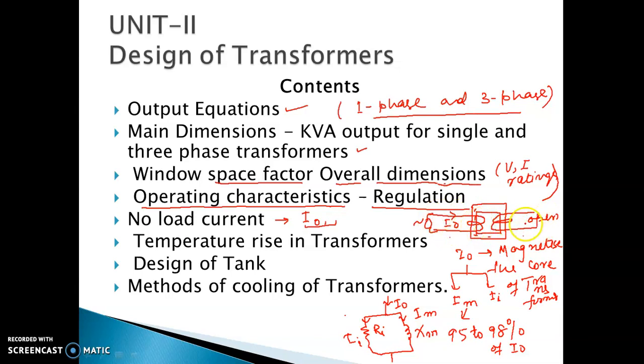If you increase the load current in the secondary side, the value of I naught remains the same, it does not change. What changes is the primary current, I1.